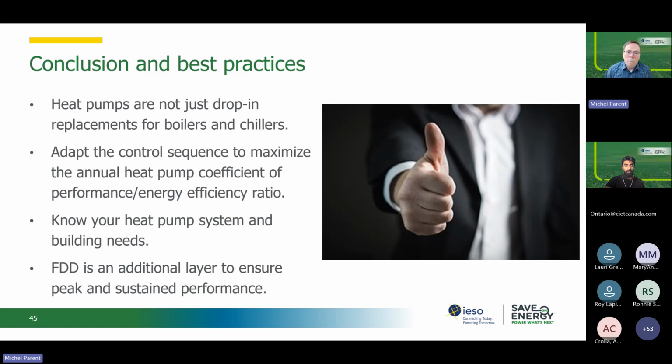The demand will go up significantly because of that backup. So usually at this stage of where we are in electrification, an air source heat pump with gas backup is usually the optimal in terms of practical aspect, reducing GHG and minimizing your cost increase.